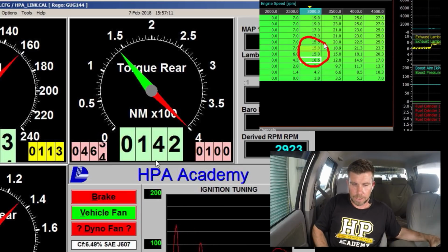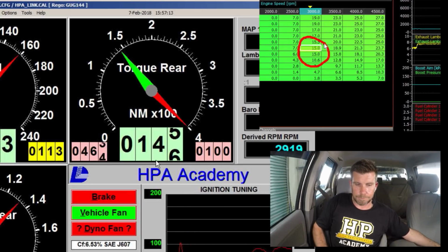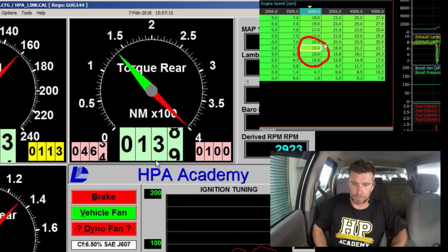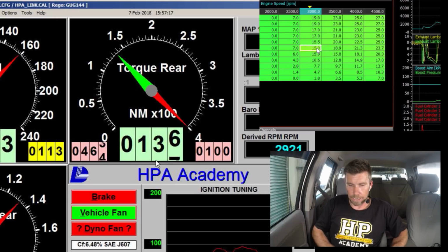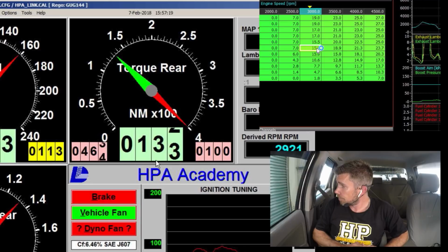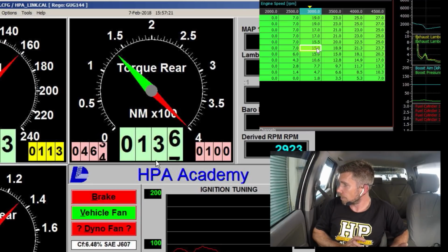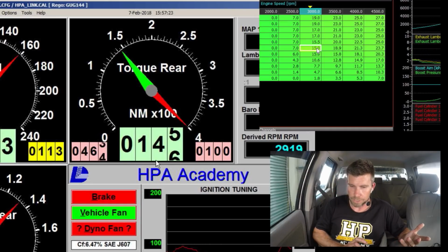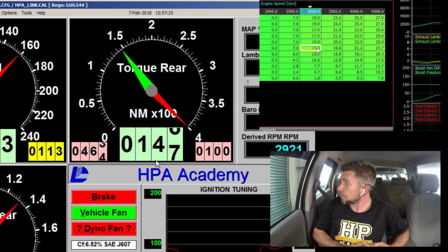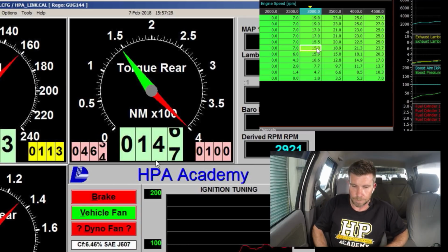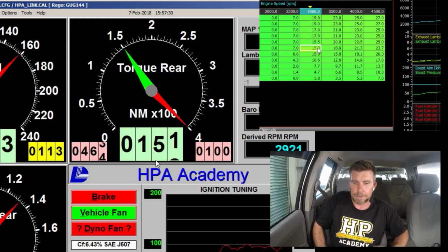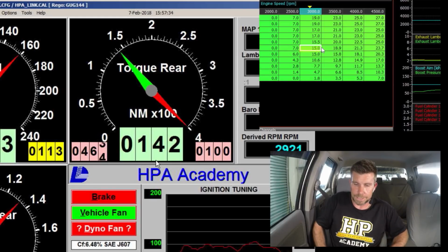Okay, so we're operating now at 50 milligrams of fuel delivery, 3000 RPM. And again, if we look over at our dyno, we can see that we're sitting at about 135, just moved around a little bit, let's say 150 Newton meters of torque. Okay, what I'm going to do now, the moment we're beginning our injection event 15 degrees before top dead center,